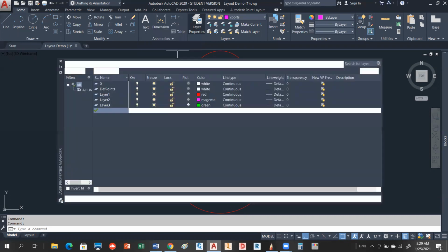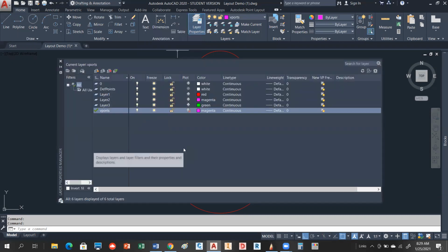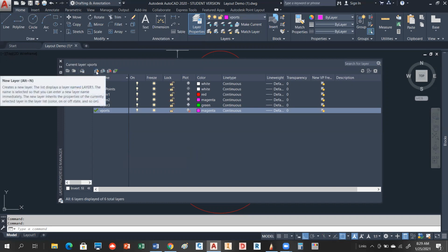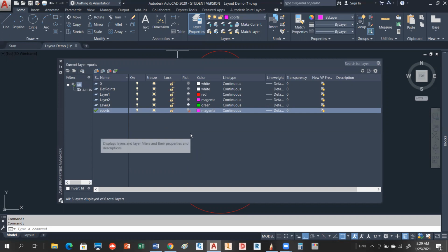Yes. Okay, click on that. It should open up that dialog box. And see over here, there's your layer creation tool right there. You just click on it, it'll make a new layer. It usually will just automatically call it layer 1, layer 2, layer 3. And you can let it ride with those layer names if you want. You can also change the name after the fact. Okay. Got it. Thank you.